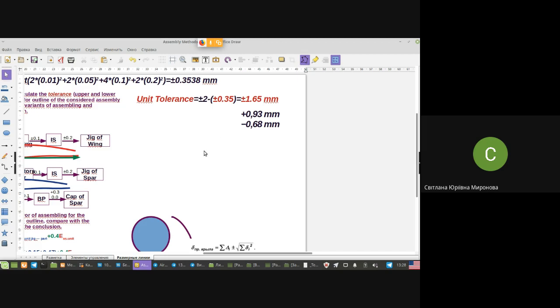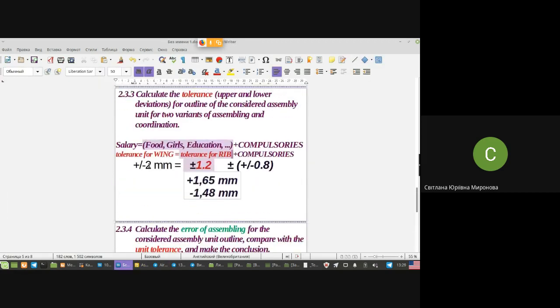In case, like it was in the previous case, limits are more narrow than the possible dispersion of errors that you will obtain in manufacturing, in this case, it is strongly not recommended to use this technique of coordination or these assembly methods. Or you should be ready for the possibility that you are spoiling your money and time.